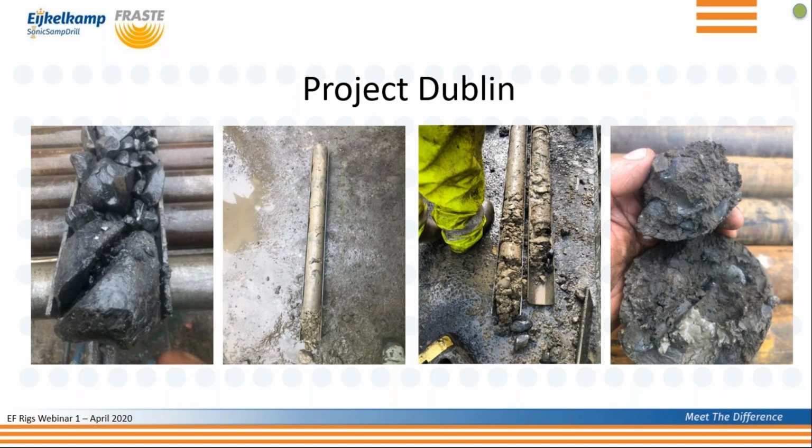Right, basically it was a mixture of sands and gravels and boulders with the odd clay lens. The SPT results were refusals all the way down continuously, and quite often you'd come up to what you thought was rock, but then wouldn't be. It'd be a big boulder, and you'd core through the boulder. Then when you brought it out, you'd see the size of the boulder you'd cored through, and then you'd go back into a loose sands and gravel type material. So it is quite confusing unless you're getting a good recovery and you can see what's there.